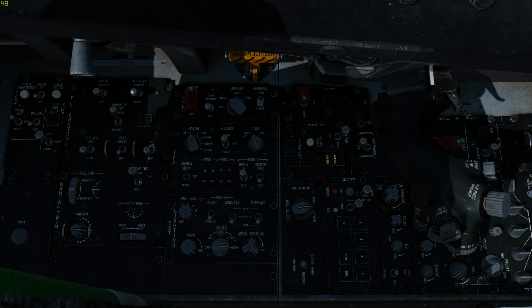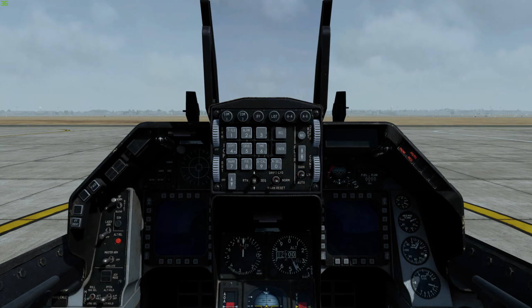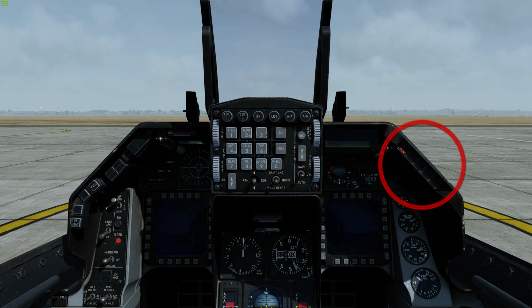The engine can now spool up alone, and the JFS is shut down, the main generator comes online, and the battery is taken off the bus. The standby generator light is off. The main generator light will extinguish around 10 seconds later. At 60% RPM, the engine and standby generator caution lights extinguish. The hydraulic and oil pressure caution lights extinguish between 15 and 70% RPM.